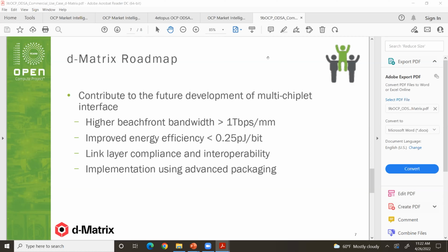So essentially, if you're building a matrix of all the different chiplets, you can put so many of them as long as they're all connected by direct straight wires. The limitation that Rishi brought up is about the IO chiplets. You have a main technology die in the center, and then you have all these IOs around it. That's where the limitation comes in, to maybe 7 or 8, 2 on each die edge.